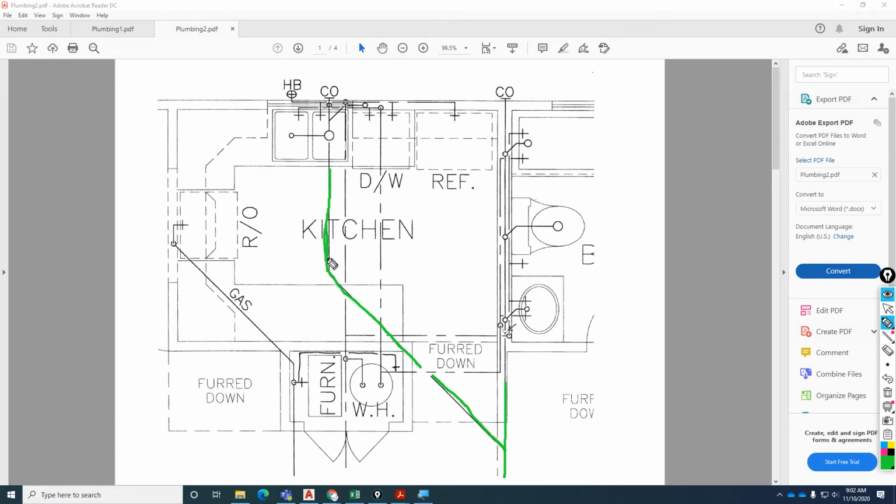One other thing to notice on sewer lines, notice the bends on sewer lines. The magic angle on a sewer line is 45 degrees. You never want to have a sewer line coming out at a 90-degree angle. You never want that. And I'll explain why on my next explanation, because this has more of a tendency of clogging. 45 degrees runs a lot smoother. 90-degree sewer lines is just a no-no. You don't do that. It's just something you don't do. Okay. So let me continue with the explanation.